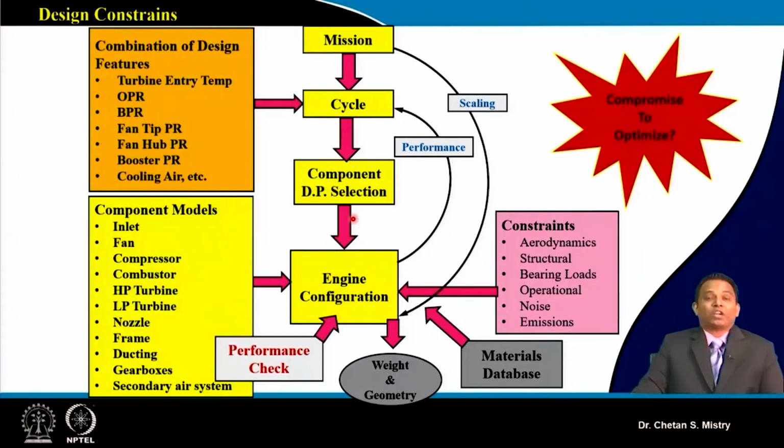Same is the case for the compressor. We will be expecting the pressure ratio to be very high. Suppose we are expecting a high pressure ratio, that means my per stage pressure ratio is very high. That will give me a reduction in length. Now the question is, in order to meet that requirement, I may need to go with special kinds of aerofoils.